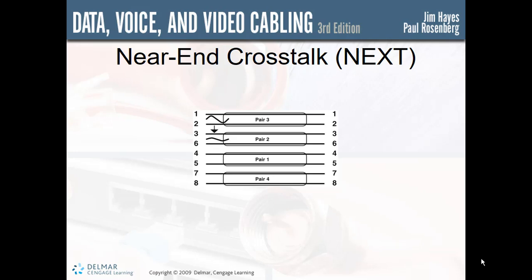Terminate the far end of each pair to prevent reflections that would interfere with the crosstalk measurements. Transmit a signal on one pair, measure the coupled signal on another pair, and calculate the crosstalk in dB, just like attenuation. As with attenuation, pass-fail criteria are set by the TIA 568 standard and are given in the following discussion on certification.